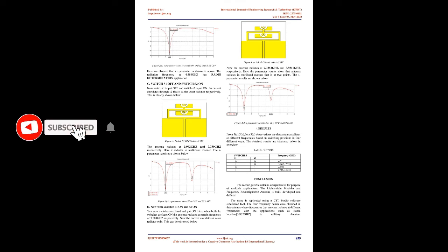The CPW feeding line is attached to the central radiator with a diameter of 1 mm. For switch S1 and S2 the interior and exterior radiators are connected with the central radiator. First of all, it is designed to feed a CPW rectangular antenna with a single 4.8 GHz channel. Within and around the central radiator, the triangle is added to achieve additional reflection frequencies whose results are shown in figure 1. Now extending the implementations with switch operations is shown from here. With these implementations the antenna and their results are shown below.